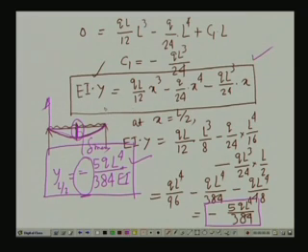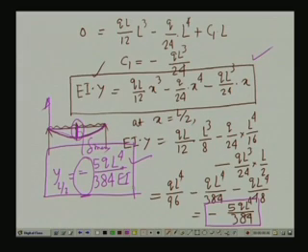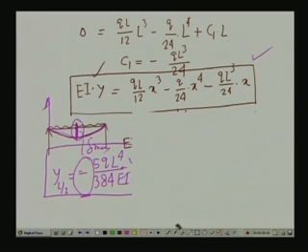Now, once we have the expression for the deflection curve, E I y equals this, we can take the derivative of this and compute the value of the slope. We already have the expression for dy dx, and the value of C 1 we have already obtained. If we substitute over here, we can get the value of dy dx. So, we can compute the value of the slope at x equals 0 and at x equals L. Now, let us compute the slope at the support points.